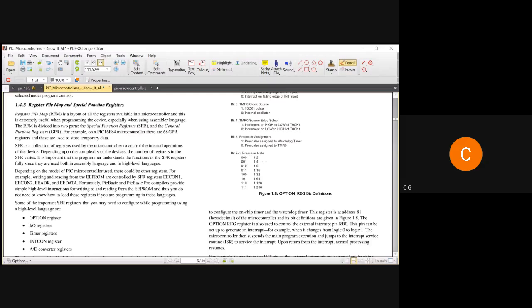In that case, you have to keep the prescaler. So prescaler will decide that for this much time duration, watchdog timer shall not disturb the microcontroller by resetting. Okay. So watchdog has its own internal timer which is matching with the operation cycle duration of a particular instruction.